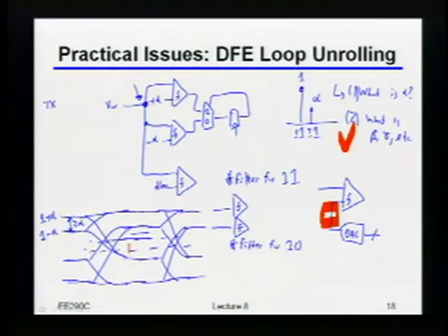Okay? Now again, that's not to say that this doesn't work. It just says if you do it, better have a really, really linear DAC. In fact, multiple very linear DACs, so that you can take a code from one DAC and use it as a code in another DAC and expect that they actually match each other. Okay? Does this sort of make sense to people? I see some slightly skeptical looks.